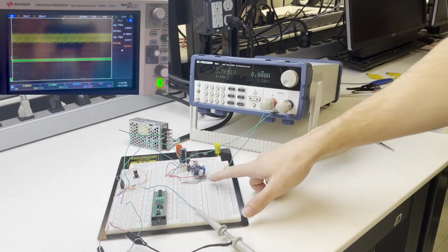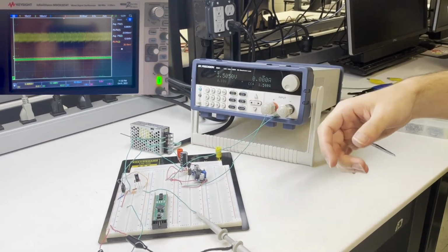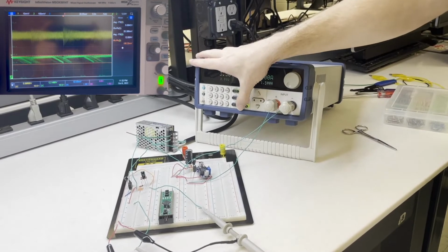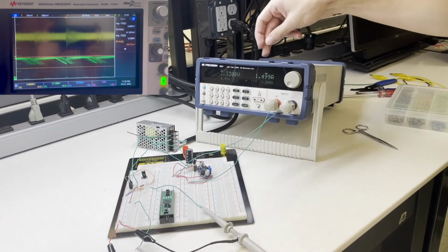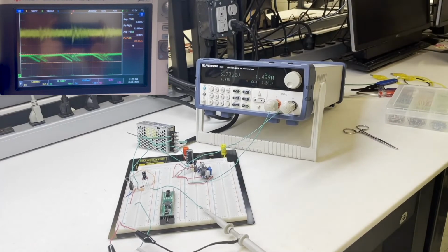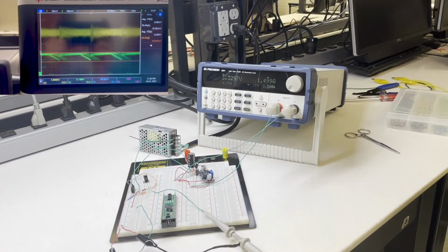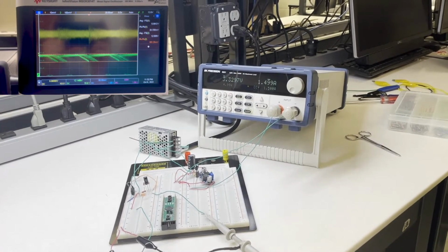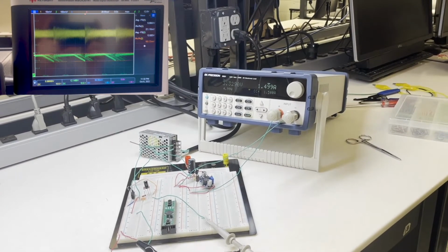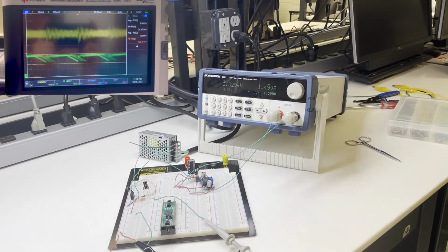Alright, now we're going to use this buck boost converter we found in the shop to simulate the load placed upon the system by what would be our buck regulator. So we're going to turn on the electronic load here. We are having it draw 1.5 amps, and as you can see in the oscilloscope, our linear regulator in yellow is still outputting the correct voltage and has acceptable noise, and our power supply is still outputting the correct voltage, and its peak-to-peak ripple voltage is still within tolerance.